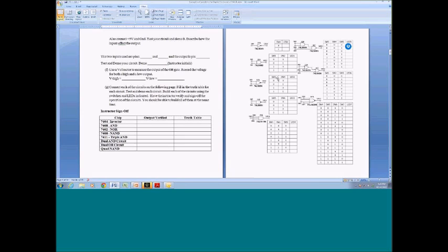But the thing about it, and this is a lot of the labs, I'm going to be changing a lot of these labs, because they're still a little bit more design focused than troubleshooting. What ends up really needing to happen in a lab like this is I almost need to give them an unknown chip. Here, wire this up and tell me what this is. Or here's a truth table, here's a circuit, these two don't match, fix it. This circuit needs to look like this truth table. So what's wrong with it? They're using the wrong gate. Maybe one of the gates is blown out.